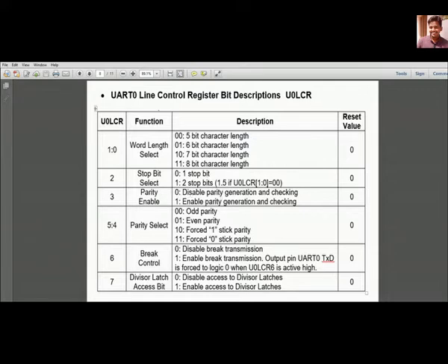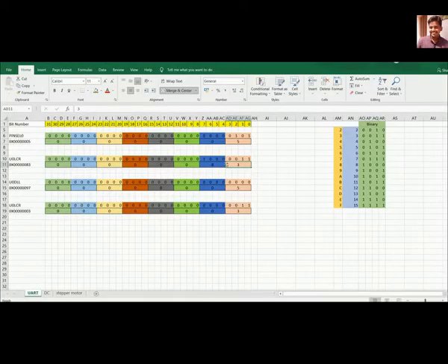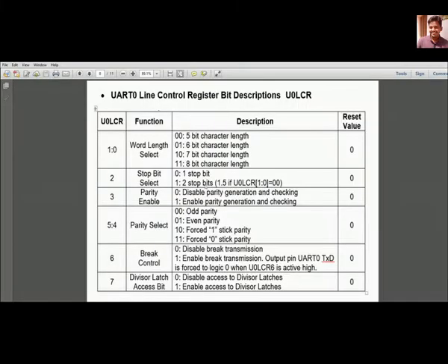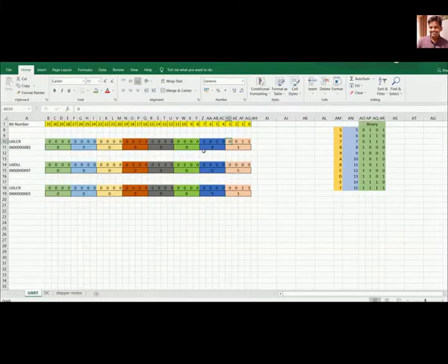You can see that the second and third bits are initialized to 0. So this is the second bit. The second bit is 0 and the third bit is 0. And what is next? This 8 value, let me tell you. This is the 7th bit. If I make the 7th bit 1, that's why I'm getting 8. You can see if I make the 7th bit equal to 1, I will get 8 in a hex value, right?